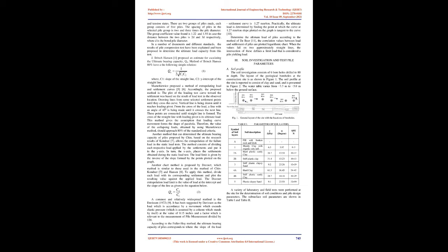Prediction and determination of pile bearing capacity have a great influence on the economic and technical factors of the construction. Using a highly reliable method in calculating the bearing capacity makes the selection of pile bearing capacity, pile cross-section, and pile length quick, accurate, and cost-effective. The correlation between the pile head displacement caused by the axial compressive load, which is shown in the graph of the pile's static compression test, is one of the bases of determining the ultimate compressive load capacity for the design of pile foundation.